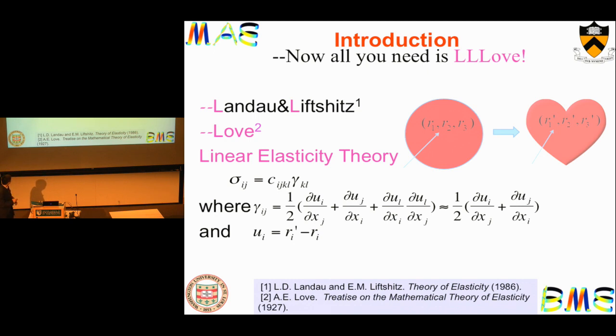And in linear elasticity theory, people just throw out the higher-order terms, and the constitutive law simply states that the stresses are linearly proportional to strains, and that's like a 3D analogy of the well-known Hooke's law. So force is linearly proportional to displacement in 1D.